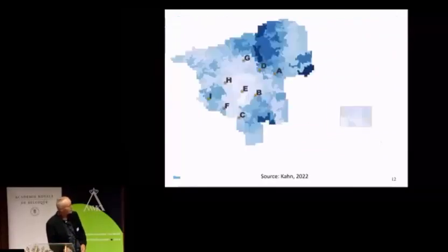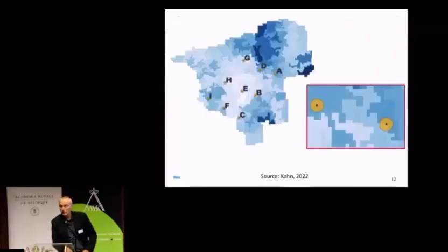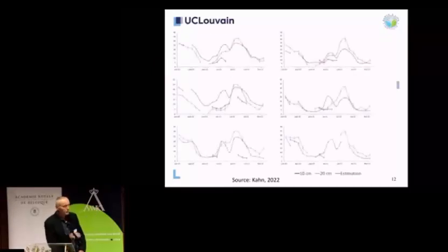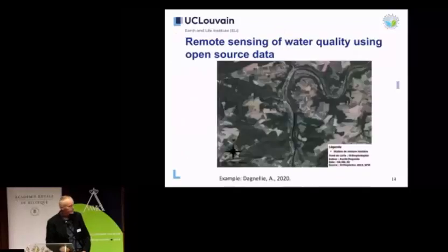Another kind of example, of course, we can use this, but where does it work? Is it appropriate? Of course, we have tested this type of technology. We installed in these type of fields also sensors allowing to measure in an independent way the soil water. And if you then compare the time series that are measured on these different probes, then we can see that it matches. Of course, it's not a perfect match, it needs to be interpreted, but at least we already have technology which allows us to monitor the time dynamics and the space dynamics of an extremely important soil variable that allows us to produce rice in a correct way in these areas.